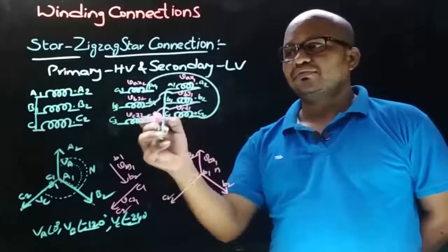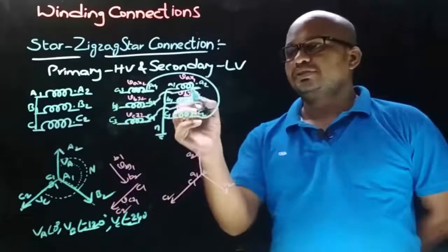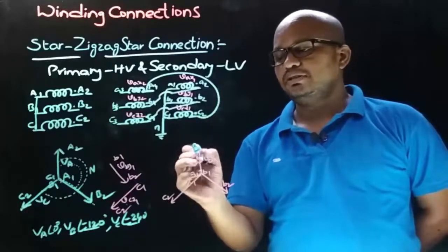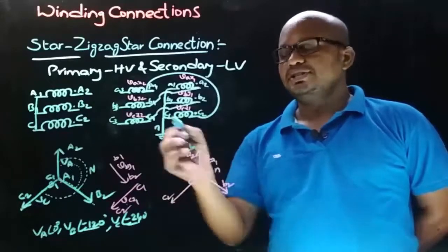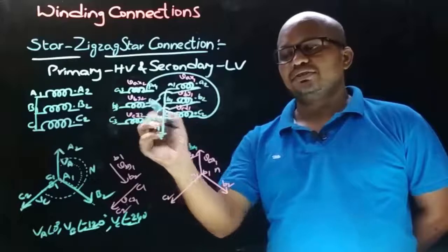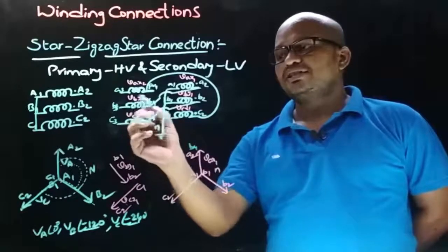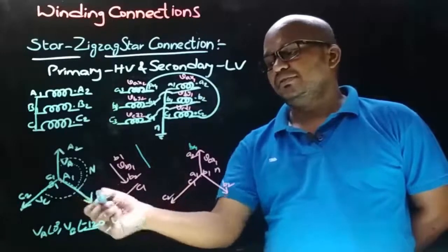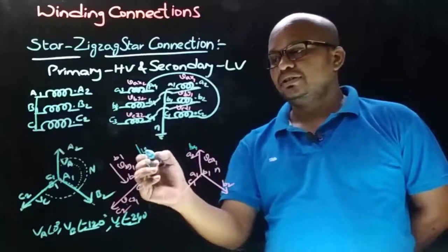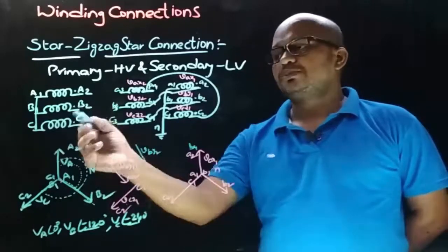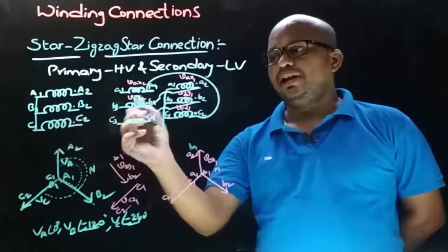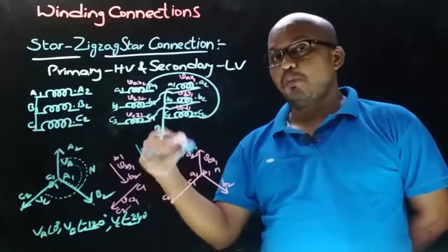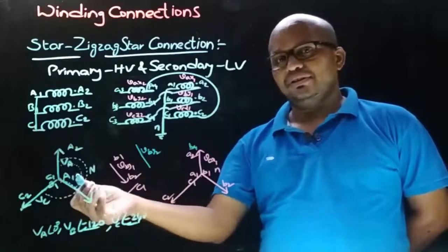Now let's draw the phasor diagram for this other half section of LV winding. Observe that here to dot end terminal A2 there is B4 connection, means to A2 there must be B4, means we must draw VBY2 phasor from A2. Therefore, let's draw the secondary side VBY2 phasor somewhere here parallel to primary side VB phasor. And now we need to decide the direction of secondary side VBY2 phasor. Observe that on primary side consists from dot end, and on secondary side consists from non-dot end, means the direction of secondary side VBY2 phasor is opposite to the direction of primary side VB phasor.